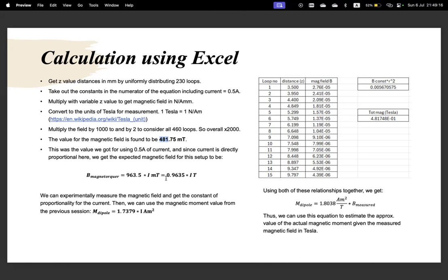Okay. So measuring the magnetic field is a process that requires one step. When I was doing the experiments for this magnetorquer, I just used my phone. I bring my phone close to the magnetorquer and check the magnetic field, then I remove the current and check the magnetic field, or vice versa.